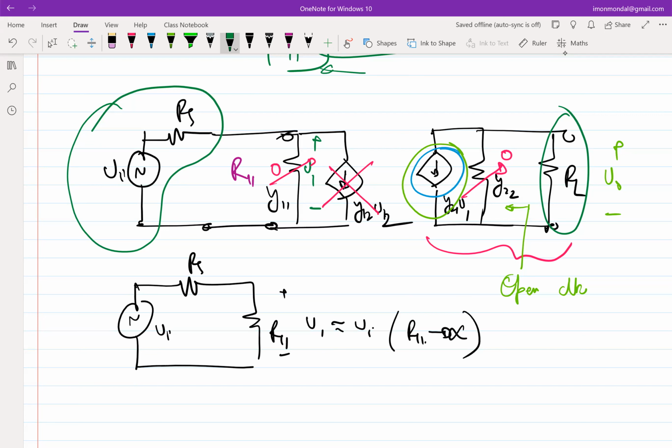So part of the motivation of the course is essentially to design this. Now you are still in this Y12, Y11 parameter regime. Later on, you will see that we'll replace them with actual devices, and then we'll see what constraints further emerge. So to cut a long story short, Vi and RS are not in your control. It's a user specification. Somebody has asked you to design an amplifier. Whoever has asked you will also give you the specifications of the input resistance and the output resistance, and then say design me something in between.